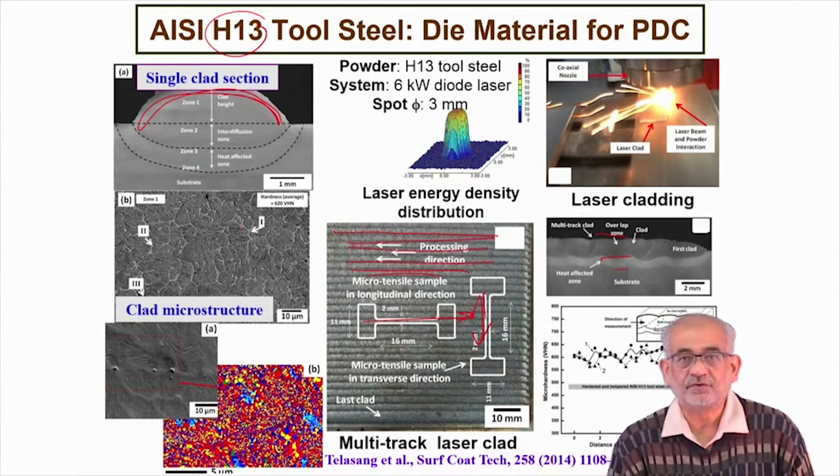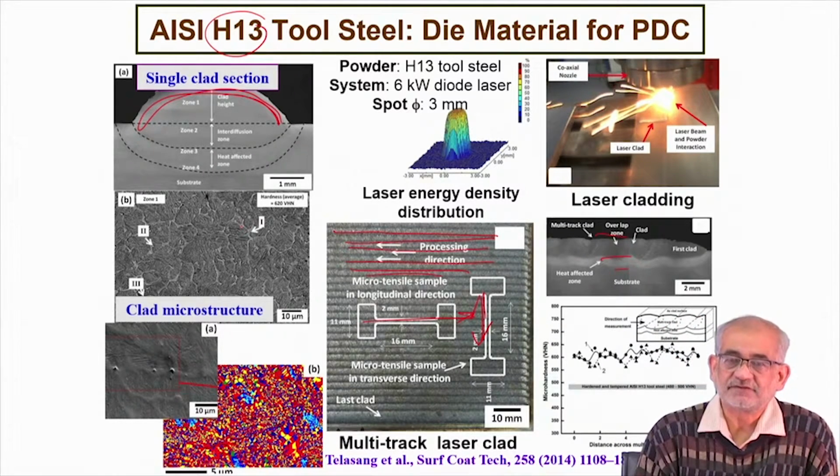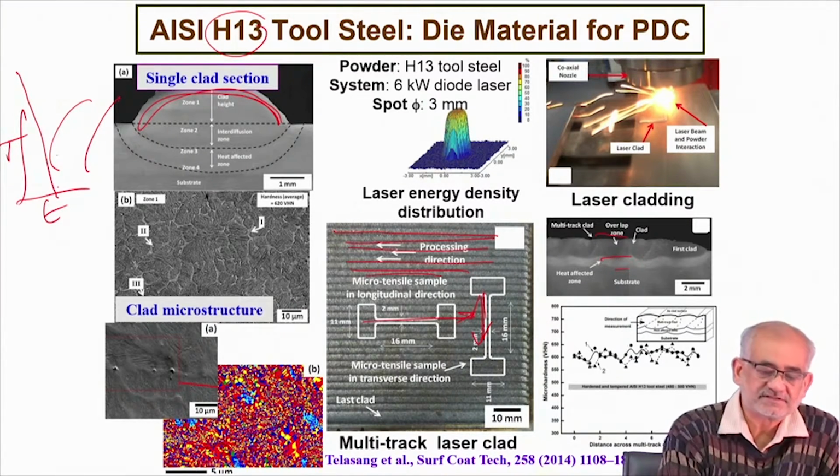You may form certain other phases, but in order to get martensite, we are aware that we must avoid any diffusional transformation. If you just quickly recall, with temperature on this axis and time on this axis, we are referring to a continuous cooling curve like this, and our cooling rate all the way must be very fast, and we should be able to avoid intersecting any of these pearlite start or pearlite finish curves.